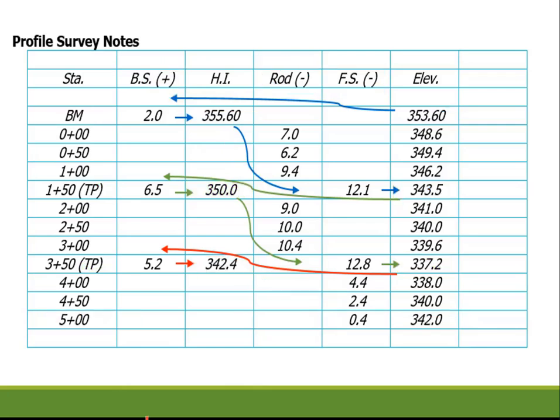So here is a clean version of the profile survey notes. Now this is an incomplete set of survey notes in that it doesn't come back to a finished benchmark, so it's not closed, and there haven't been any adjustments made otherwise for those elevations.